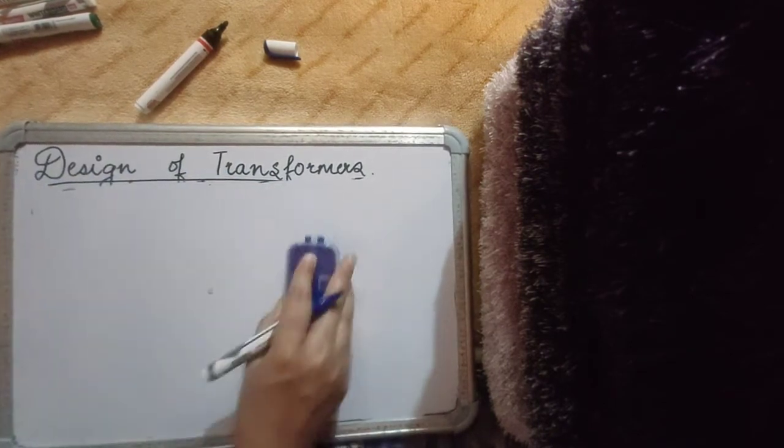Now finally, let's talk about designing a transformer core. When we are designing a transformer core, we have to take care of the turns ratio N1:N2, depending upon whether we require step up or step down action. We will also have to take care of the dot conventions to make sure that the polarities are as per our requirements. Apart from that, there are two more constraints that we have to take care of. One is of course the constraint on the maximum current, depending upon the maximum field strength allowable in the core.